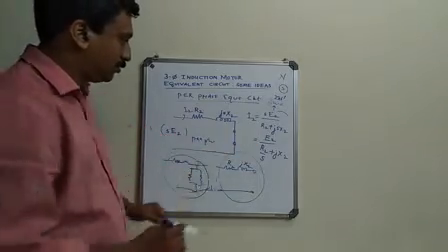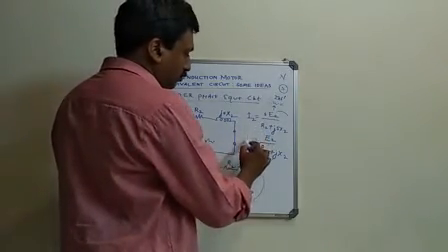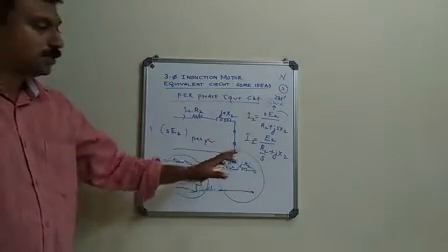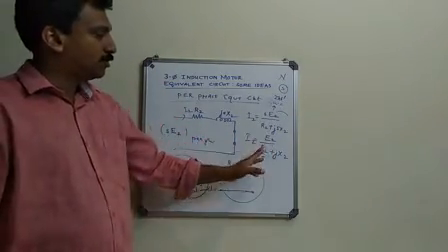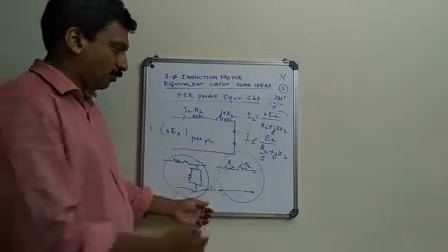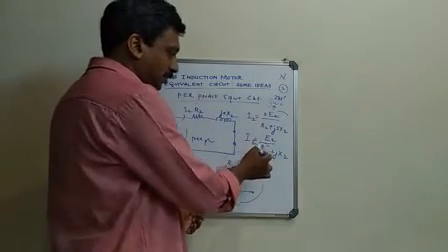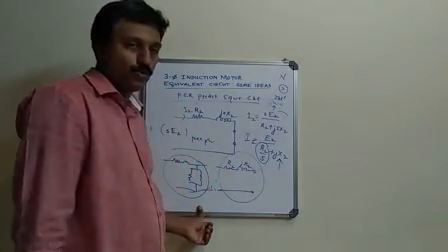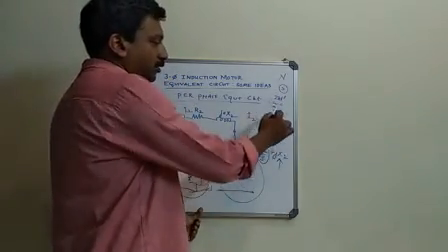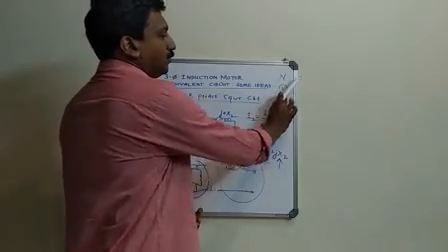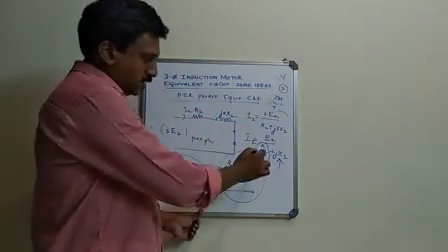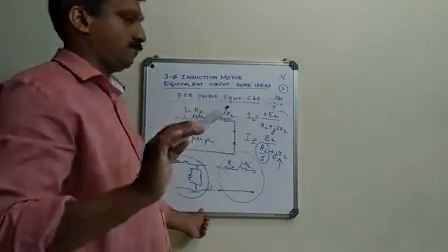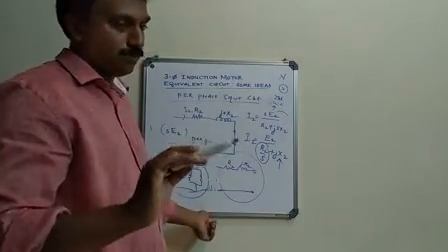The same situation: this I2 you obtain in the same way. But here, you can definitely say that it is at the supply frequency, with omega being 2 pi f, not f dash, and E2 is not SE2 but E2 itself, the standstill voltage, for the same frequency.